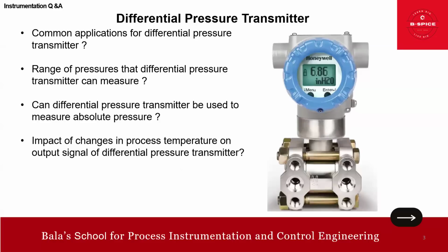So the answer is yes, temperature changes impact the output signal. Nowadays, most differential pressure transmitters include temperature compensation to minimize this effect. That is the point.